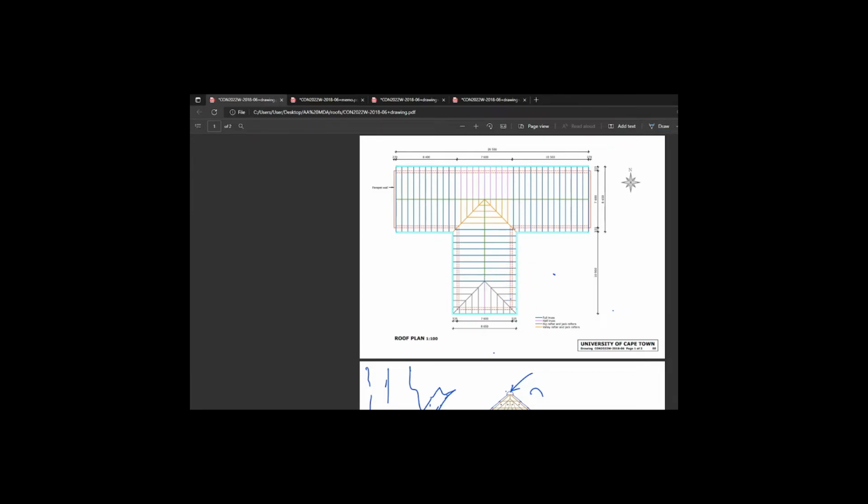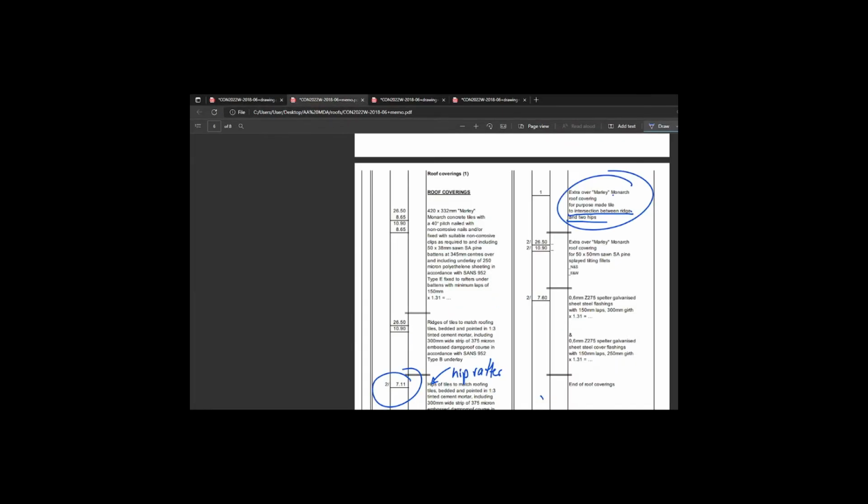What I want to say is just assume if there's a nice intersection at 1, 2, and 3 raised ridges, we will put a purpose-made intersection tile. If there's 1, 2, 3 but depressed intersections meeting it, exclude a purpose-made tile. Maybe it's something else that goes there. I cannot tell you. Let's move on to